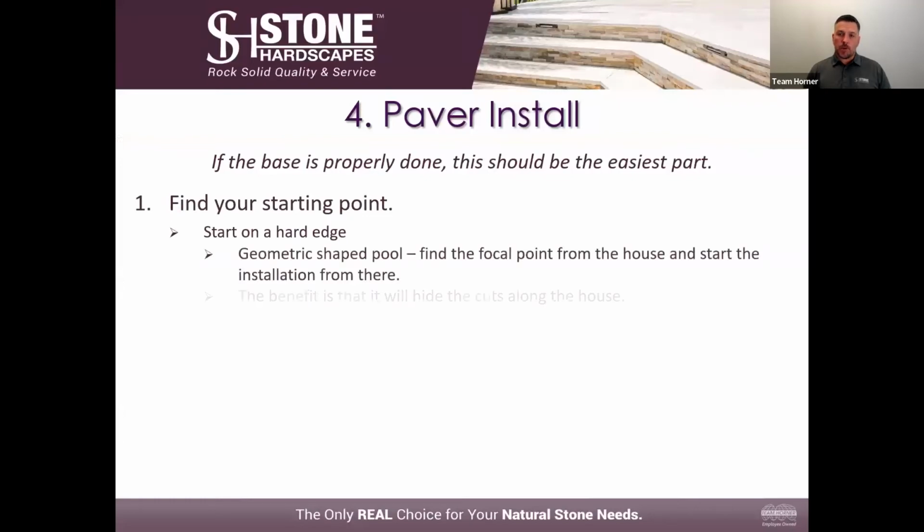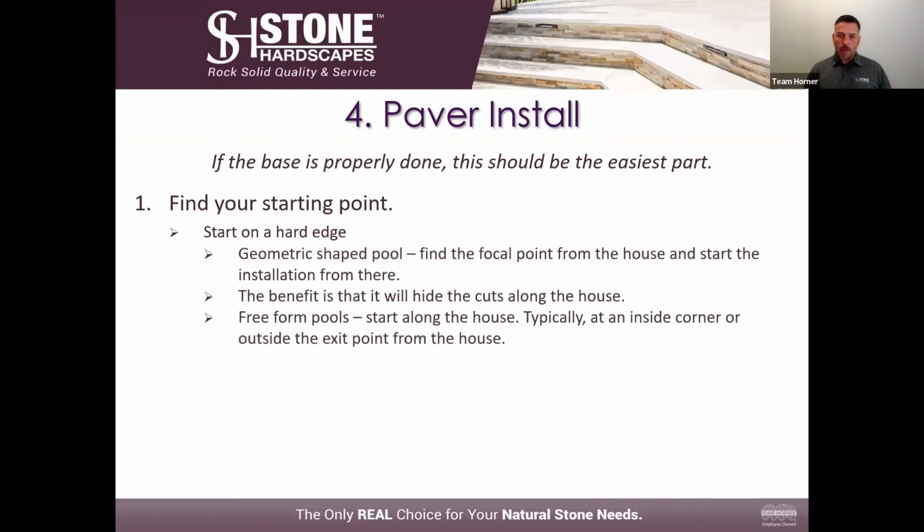Now comes the fun part. If the base is done right, the excavation's done properly, and the bedding sand's done properly, laying the pavers should be your easiest part. If the excavation's wrong, the base is wrong, and the sand is incorrect, laying the pavers is going to be difficult, because you're going to be fighting the elevation and the pitch the entire time. Laying the pavers, once everything's done correctly prior to, should be like putting together a puzzle.